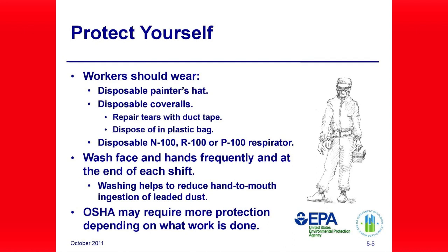You should wash your hands and face at the end of each shift or periodically, before and after eating, drinking, or smoking, or leaving the work site. Personal protection is especially important on high dust generating jobs when lead-based paint or lead-contaminated dust is disturbed and while cleaning is being performed. However, the same level of protection is not necessary during the planning, testing, or setup phases of the work when lead is not being disturbed.